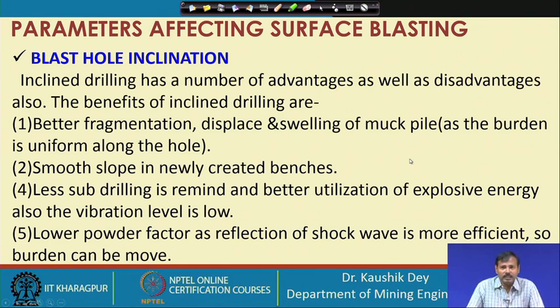Blast hole inclination is a parameter that affects surface blasting, but often we neglect this one because the inclination often induces more drilling error in the practical field. So, inclined drilling has a number of advantages as well as disadvantages.